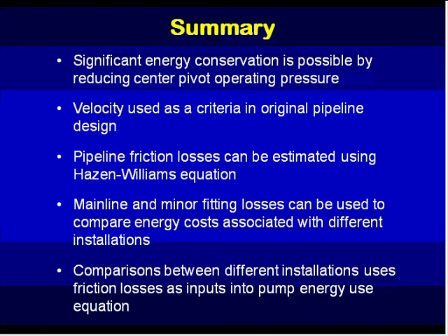Well, I think that one can use the pressure gauge. Most of our systems, at least the ones that we have in Nebraska, will have places where one can attach a pressure gauge. One at the pump outlet, our mainline check valves we use for chemigation, and most systems have on them anyway, have an outlet that you can attach a pressure gauge to, even if you have to use an adapter to get to a faucet type of thread, but you can do it there. At the pivot point themselves, there's generally a drain plug or other access point where they would put a pressure sensor in that one could potentially use.